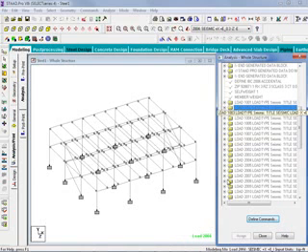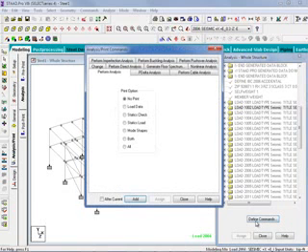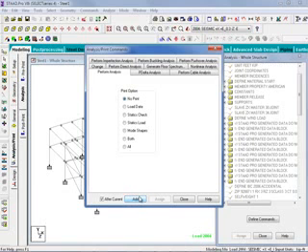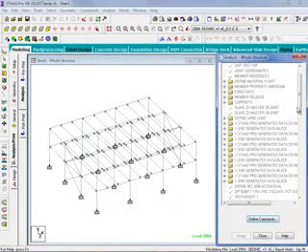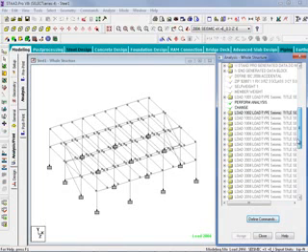To do that, we've set our cursor location and click on the Define Commands button. Now we'll select the after current checkbox to insert our analysis command. We will select our print option of no print, and then we will click the Add button. We will then go up to the Change tab. Again, our after current checkbox is selected, and again we'll click Add. After we've completed that, let's go ahead and click Close and check out our analysis dialog to see the commands